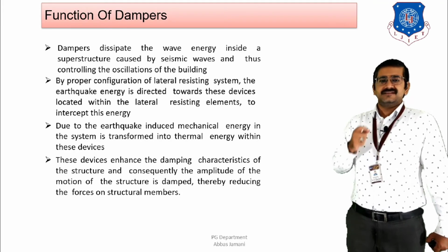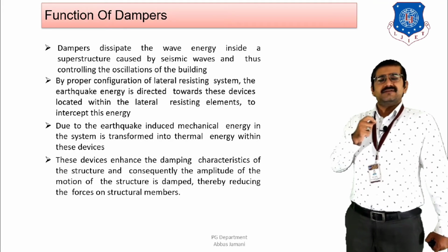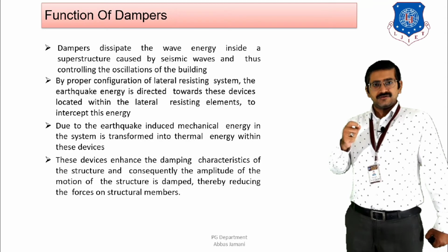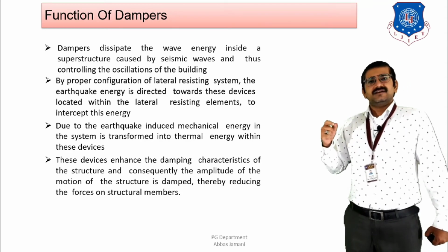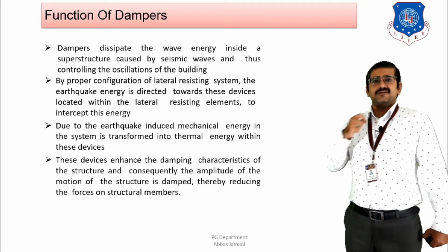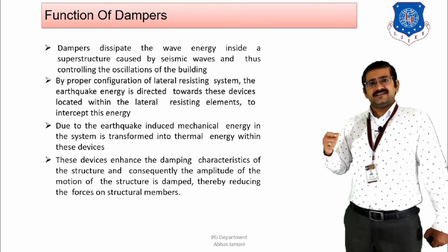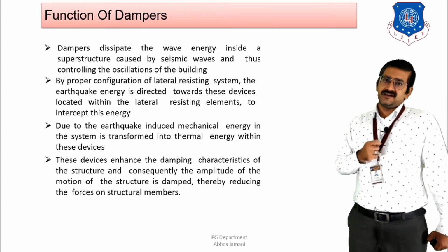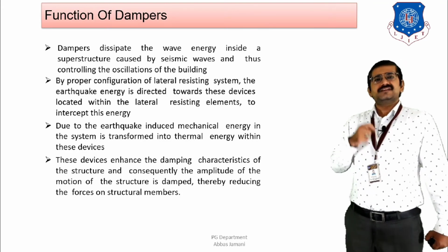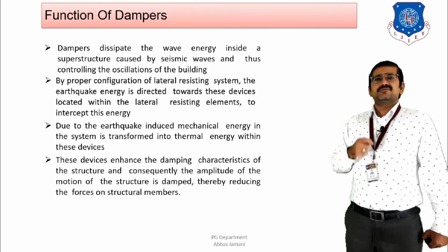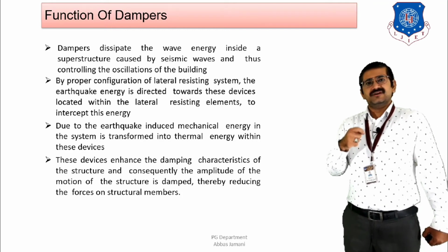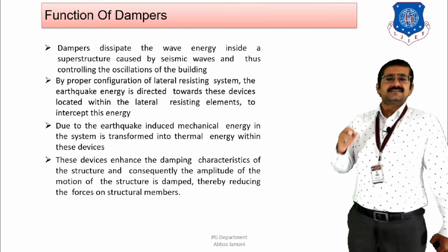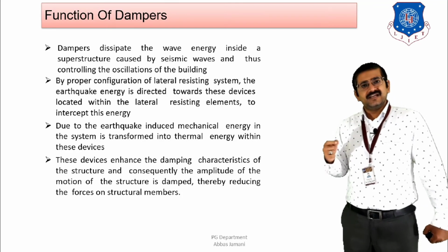these devices are going to intercept the earthquake energy that is transferred from the ground, and they will dissipate this energy, that is, convert the seismic energy to either heat energy or any other form of mechanical energy. And as a result of this dissipation of energy, the amount of forces that will be transferred to the structural elements will be much lesser as compared to buildings without dampers. And as a result of that, economy in the building will also be achieved.